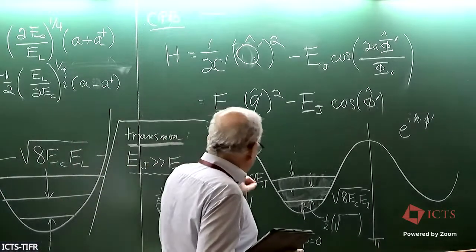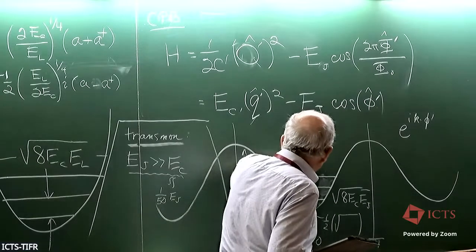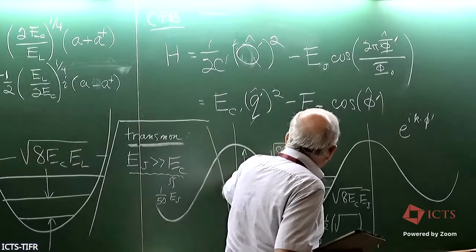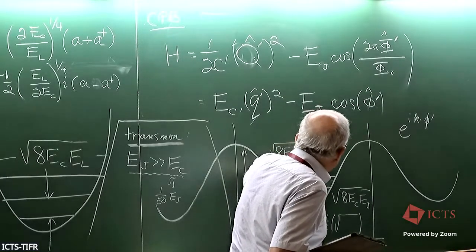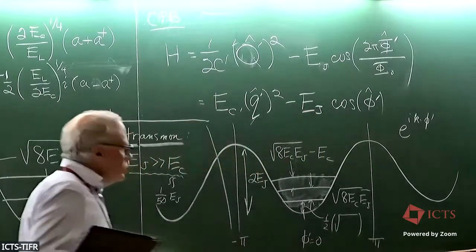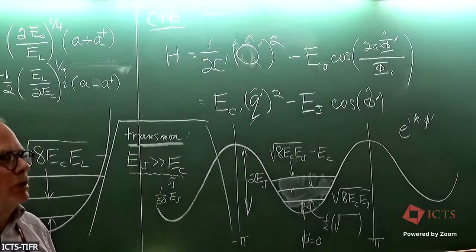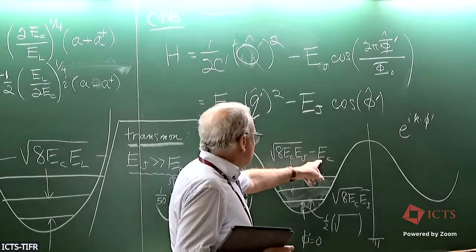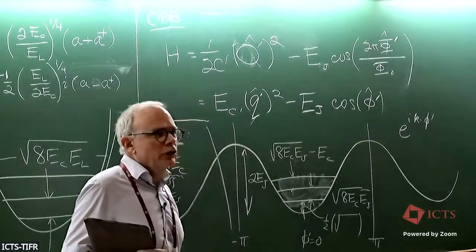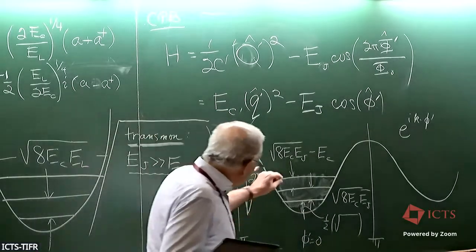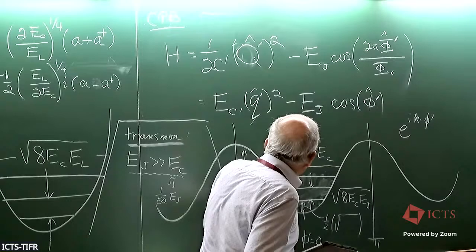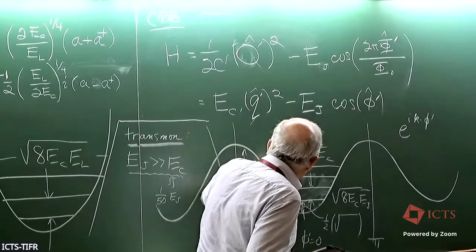Okay, now in the transmon regime, the next energy spacing is almost the same. It's almost again 8 EC EJ. It's just a little bit smaller, minus EC, it turns out. So I'm summarizing; one could of course spend a much longer lecture working this out. I will give a hint of why these numbers are the answer when you get to the second quantization of this. So this is a little bit smaller, and then the next one's a little bit smaller still. I guess the deficit is now 2 EC.